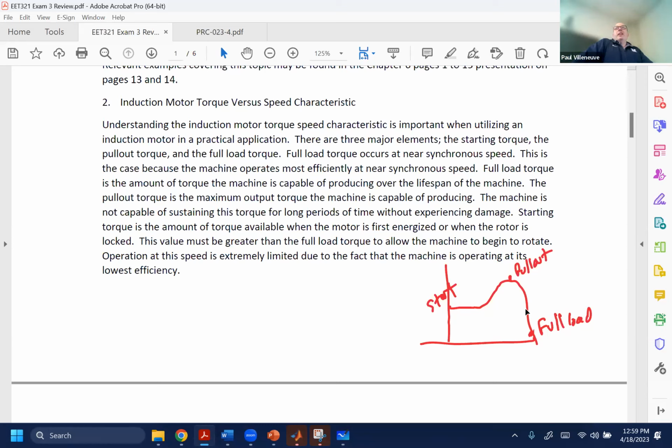It's very difficult for the mechanics, not the auto mechanics, but the mechanics that work at mills and all that stuff. They have a tough job. And electrically, I tell all people that everybody's petrified of doing electrical work, but it's so much easier. You don't have to worry about shims when you're running electrical. You just wire up the motor in the junction box. If it's spinning the wrong way, okay, just swap two leads. As long as you tie it down and it kind of looks okay, that's it. But the mechanicals have a much harder time. They have to worry about alignments and stuff like that, that electrical engineers really don't need to worry all that much about. So we have it a lot easier.